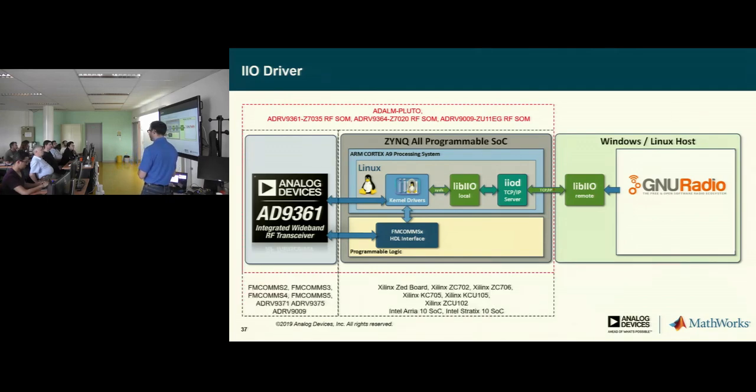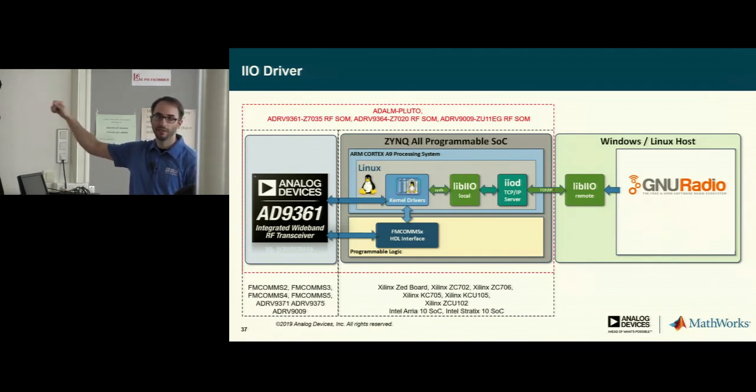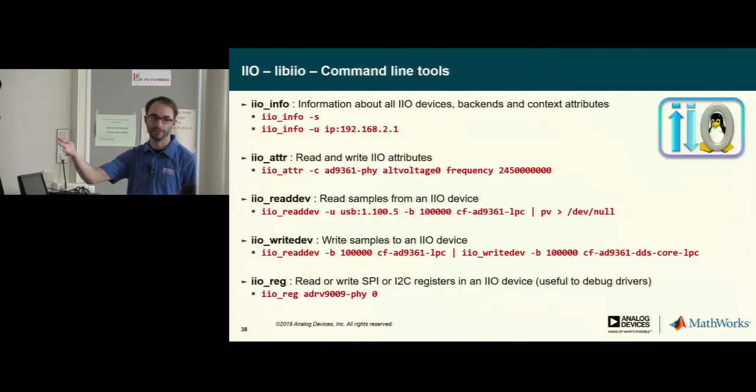So this could be a Pluto device, one of our system on modules, which have an integrated transceiver and FPGA, or an eval system. Can we use the IOD, running standalone on the board, to also send data at the same time? Do you mean send data back to the host machine? No, you can't insert stuff into that layer. You would have to modify the driver to essentially do that. It's really not meant for that purpose.